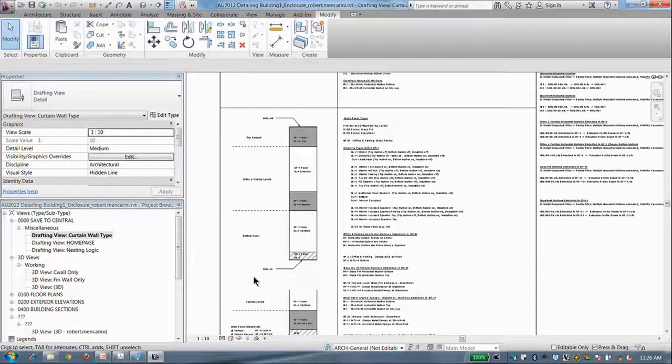The question is, how do you show the embedded information when you're working on a curved building? And the part you didn't mention is the work planes, right? You sort of draft it in one work plane, and the section might be in a slightly different angle to that work plane. You don't see it. What you need to do, and actually on the London project where there were a lot of angles involved, they had to be very careful that the sections and the callouts were parallel to the work planes where the other information was. And they had a few problems where that changed throughout design, and they actually had to rip stuff out, the views and whatever, copy and paste stuff, and make sure that stuff was always parallel, because Revit doesn't handle that well. All the views to show stuff from one view to the next has to actually be parallel, otherwise you don't see it.